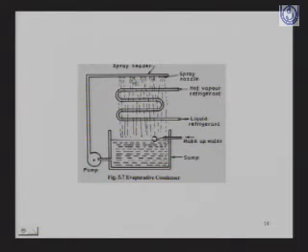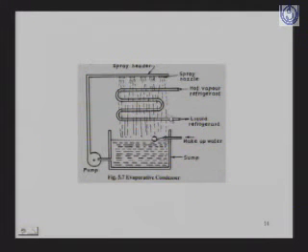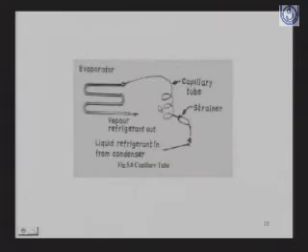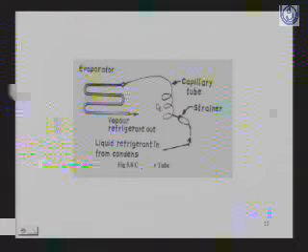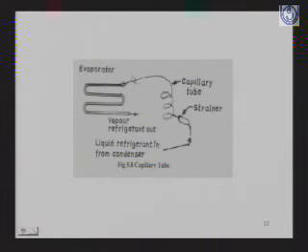Because this cooling water takes the heat once it evaporates, it takes the heat of evaporation from these coils, and the vapors are changed into liquid refrigerant. So this is known as the evaporative condenser. Then the next important unit is the expansion device.